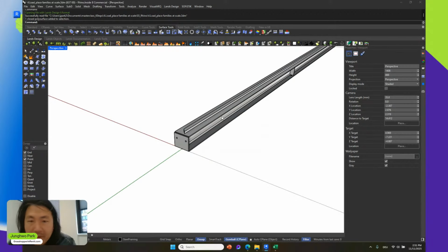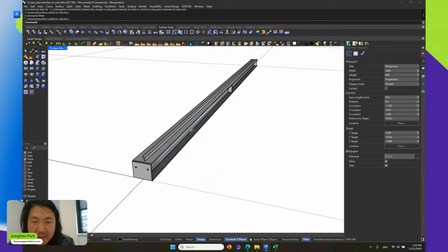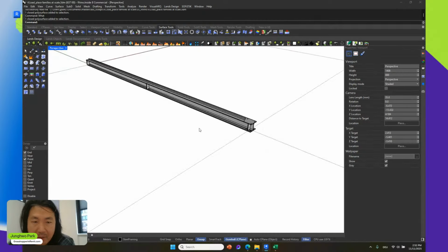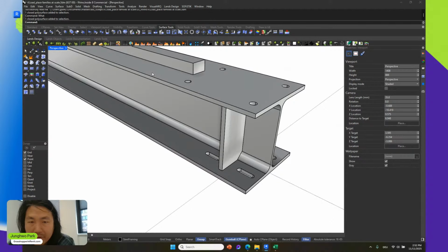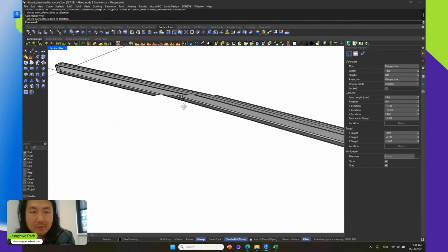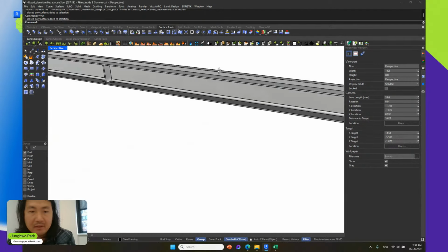And we want to create this steel framing as a native Revit family. Of course, you can do it in Revit, right? You can model, you can extrude, you can subtract this geometry using void extrusion, and you can add this kind of stiffness detail in Revit.